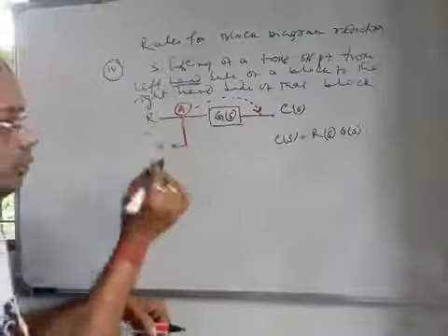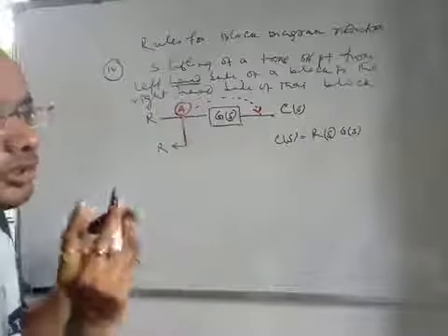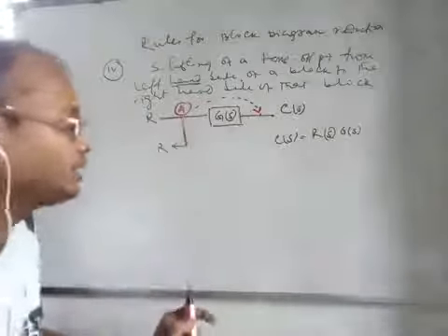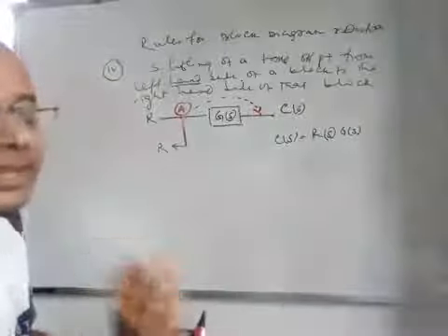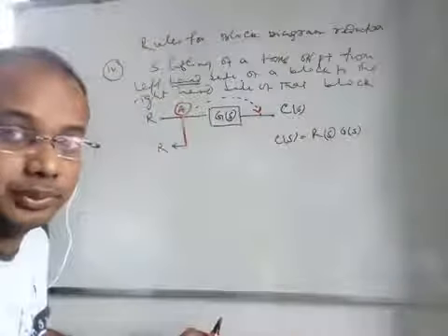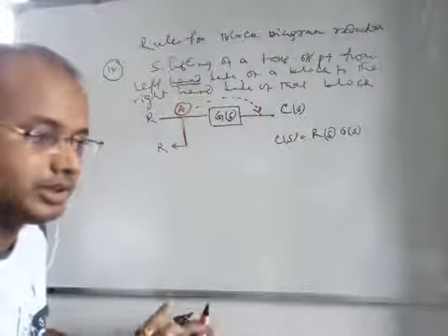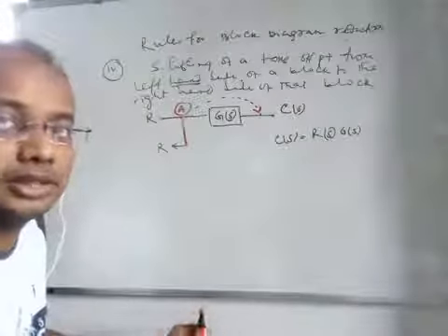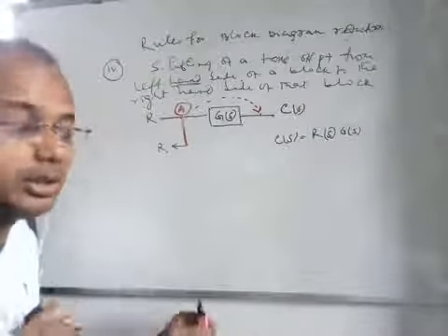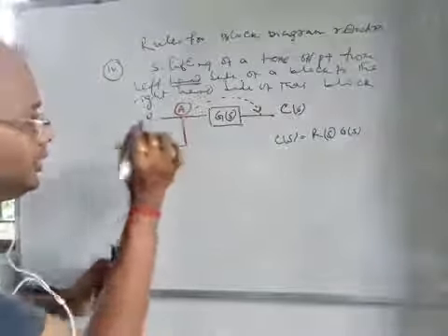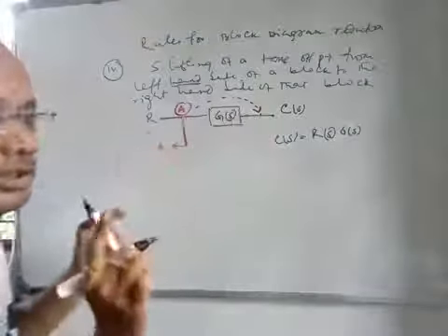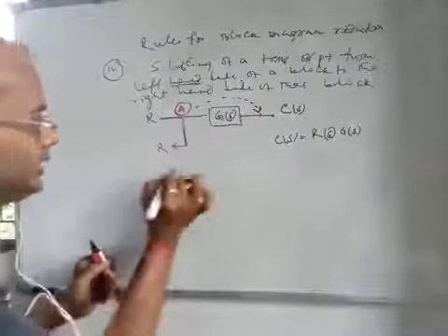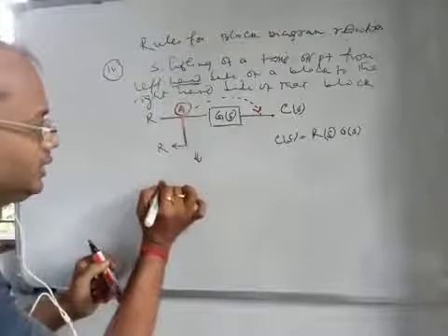Now, the main rule you have to keep in mind is that whenever you are shifting any point, maybe a takeoff point, maybe a starting point, from either side, that is from left hand side to right side or right hand side to left side, we have to rewrite the blocks without changing their value. Right? How will you write this R?